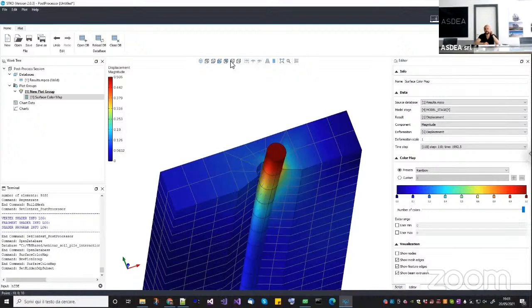The problem is that the loads on the elements are applied instantaneously, and this is a huge problem when you have contact. Because, for example, if you try to run the vertical analysis, the self-weight of the pile, with a single step, you will see that it will not converge. So yes, this is a solution, but on the other side, it is a problem with contact, and it will cause you issues with nonlinear solid material models too. That's also true.